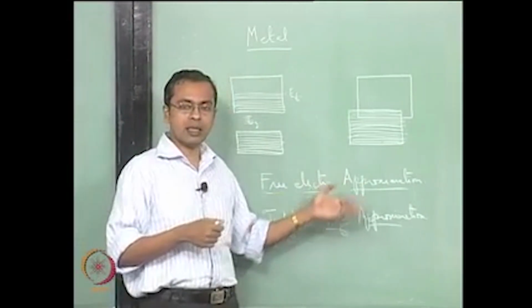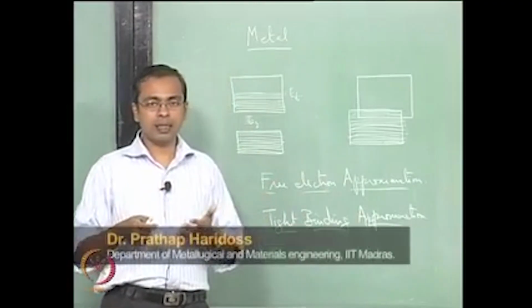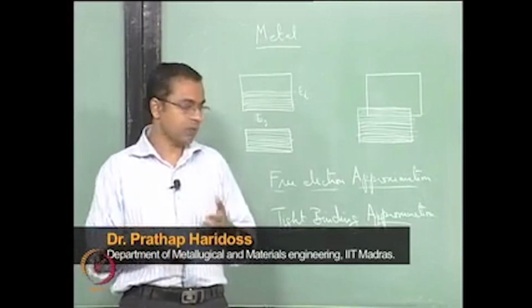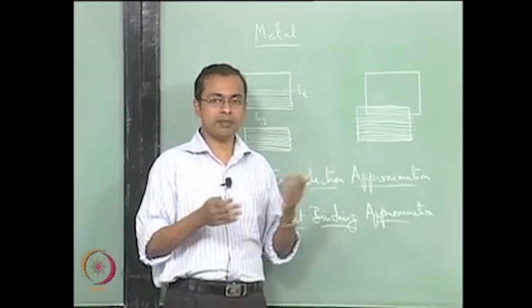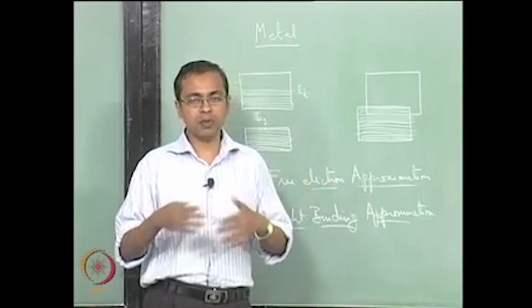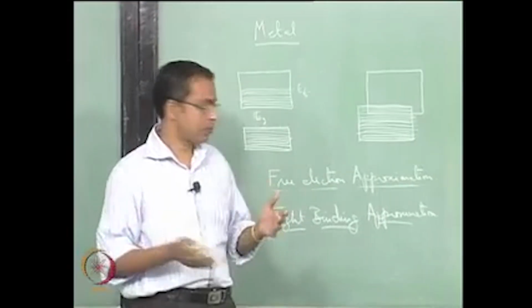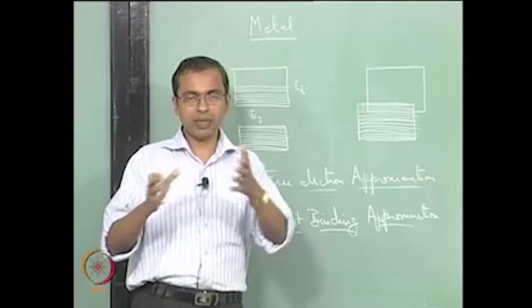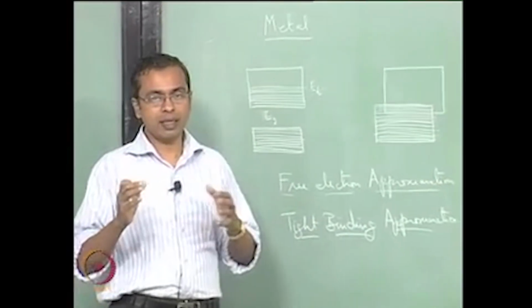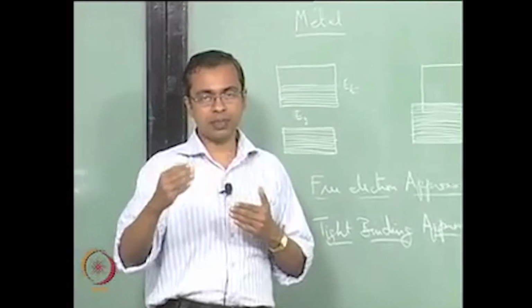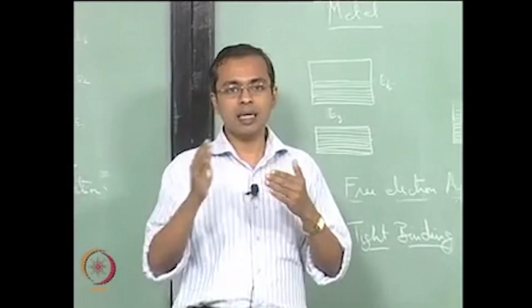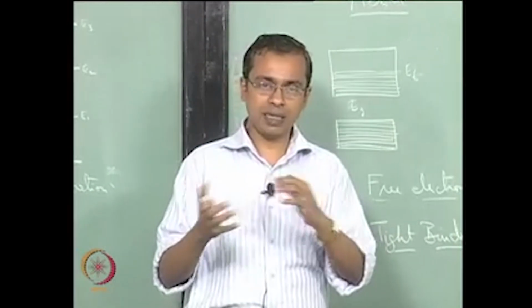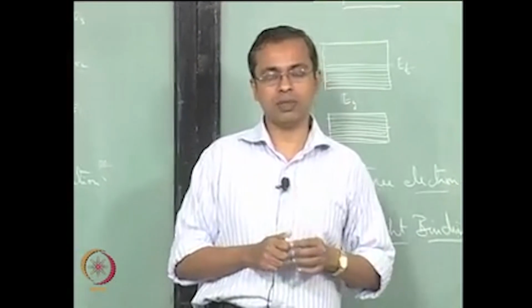So both these approaches can also convey to you the fact that anisotropy can exist in a material. Okay, in our earlier models, we were unable to show you anisotropy because we assumed a uniform number of free electrons per unit volume. These approaches can actually show you the anisotropy. Certainly the free electron approach, when you take into account the fact that the Brillouin zone is at a different position based on the structure, its interaction with the Fermi surface can occur at different locations, and therefore the properties can change.